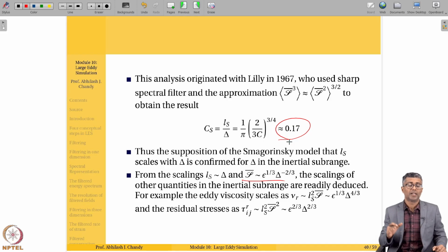So you would think that that version of the Smagorinsky model is more powerful or more accurate than the classical version. So now that the Smagorinsky model has been derived, we can substitute it into the filtered Navier-Stokes equations, and your equations are closed. You derive an equation for U bar. So in the next class, what we'll do is we will look at some limiting behaviors of LES and close it out. Thank you.